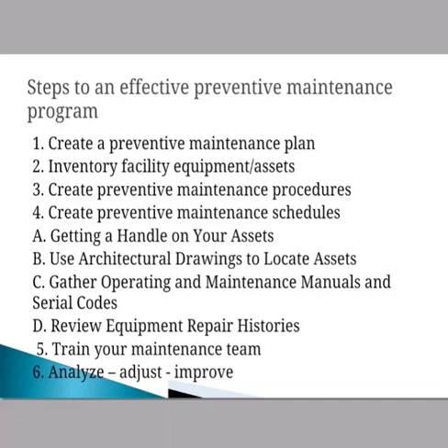This is very important. In that, the first step is to create a preventive maintenance plan. What are the different electrical systems present in the operations? We have to consider whether a motor is working or a transformer is present in the system, and according to that we have to plan the preventive maintenance according to the time, that is monthly, daily or yearly. According to that we plan the preventive maintenance of the equipment, and who will be involved in the preventive maintenance is very important.